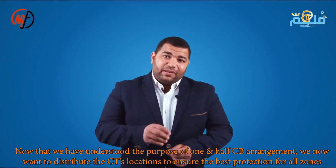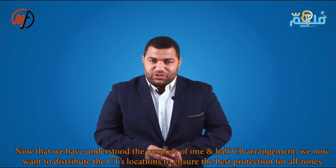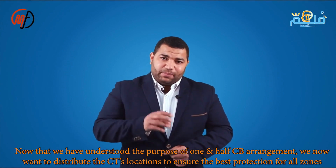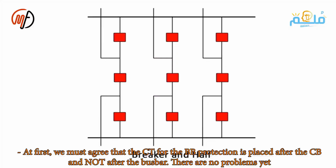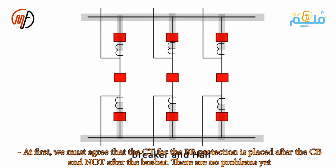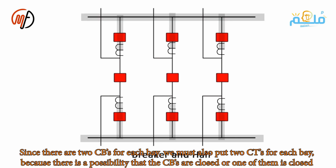Understanding the purpose, we aim to distribute CTs for optimal protection. CTs for busbar 1A and 1B should be placed after the circuit breaker, not directly after the busbars. Each busbar has 2 circuit breakers, so we place 2 CTs for each, considering both or at least one breaker could be closed. We can connect the 2 CTs in parallel before the relay or separately and combine them in the relay via software. Some stations use 1 CT, creating an unprotected T-shaped area, a dead zone.